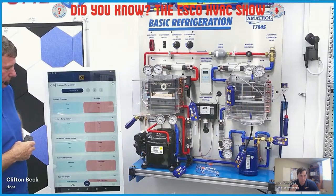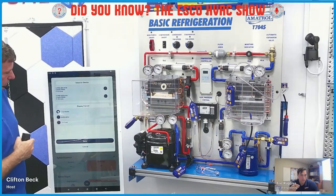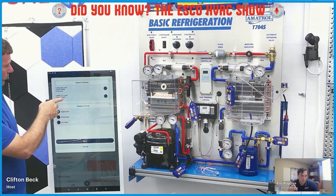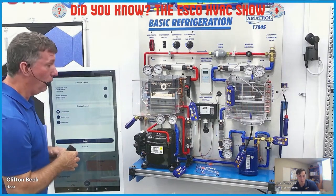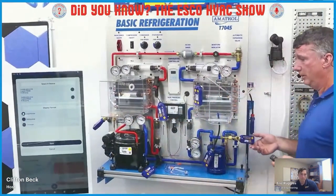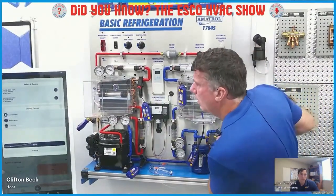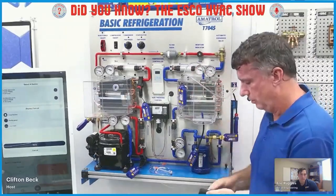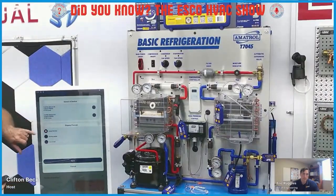So you're going to click on the low side, one of the blue bubbles. And then you're going to pick which sensor, one of the top two. Click the radio button of the one that's low. You can look on the back of the sensor to find the serial number. If the system's running, I may do that. Yep. Let me walk over here. I'll look on the back. I'm just going to swivel this one around. 9104. Yeah, there it is. So 9104 is our actual low side. So I would pick that one.